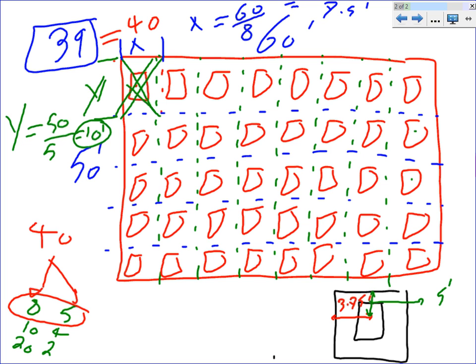I just want to emphasize that, guys, the end of this fixture is actually minus 1 foot. So in reality, this is 2.75. Here's a 2. I might have to drop the 2.75 if I want the edge of the fixture. Instead of 2.75, I might have to start at 2. Anyway, if it's a 2x4, very helpful. Ultimately, my friend, you need to play within the grid if you have a grid. If you don't have a grid, this calculation will get you as close to a great design as you can.